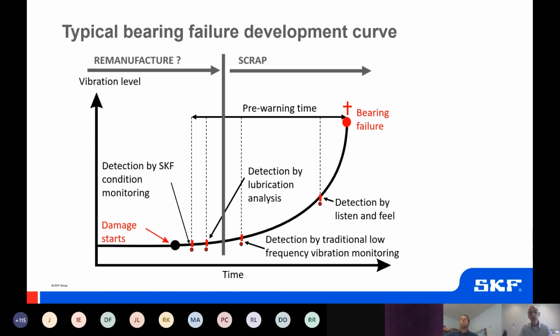And maybe the easiest example to use here is that you may have a bearing that is running over lubricated, and that means that the temperature will develop very quickly, while your vibrations may not give you any indication that there is a problem. So it is important to have a multifaceted approach, and one of our sessions will, in the next few days or weeks, cover that. You need to have the right strategy to give you the earliest indication so you can catch the failure when you can really understand what has started the process. That's the key.